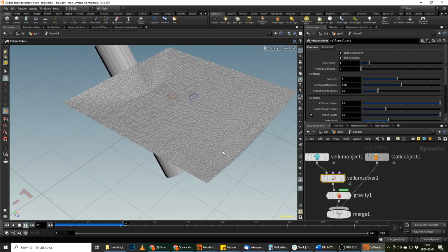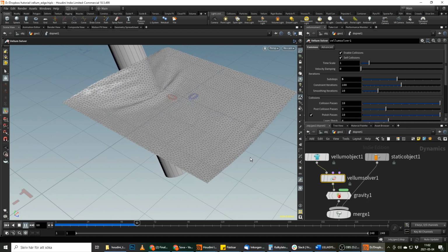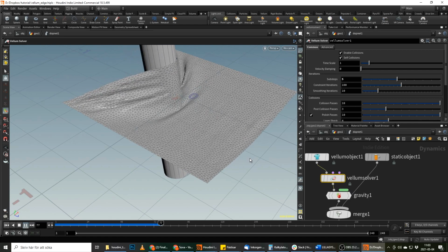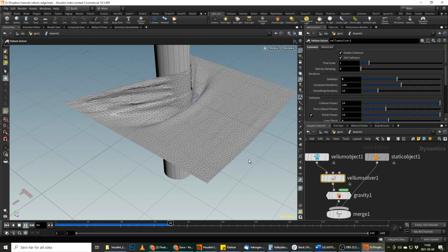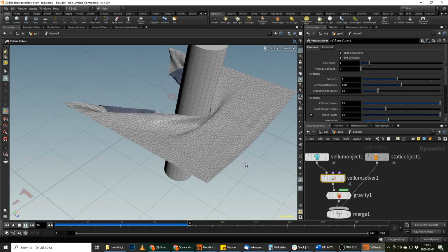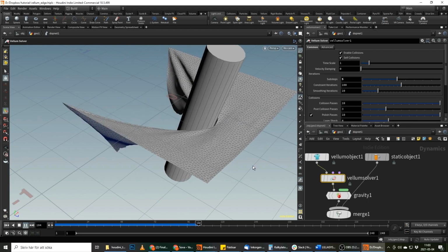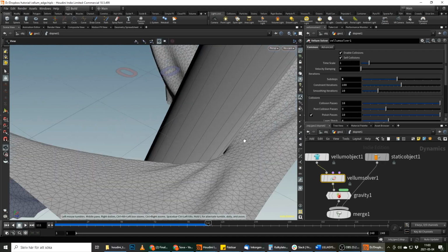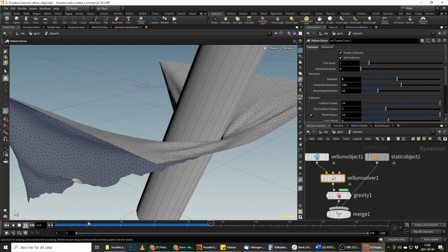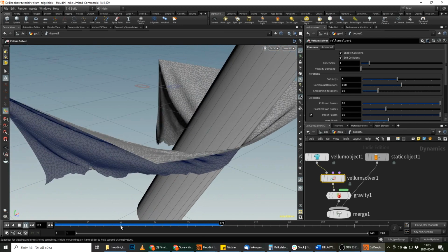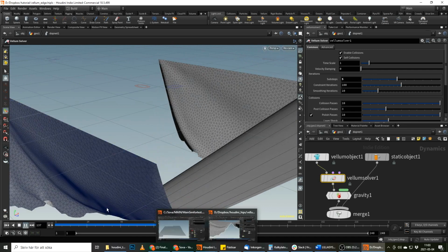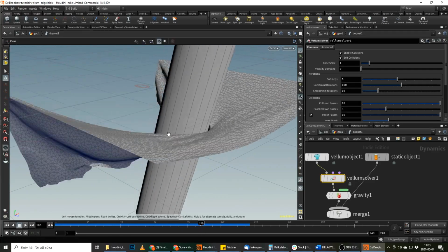It's very floppy still. We could also add a little bit of velocity damping in the solver. Let's see if it breaks here. It breaks quite late, but it breaks. So there we go. Seems to be working. Quite nice. Yes, it works. It actually solves it quite well with this.